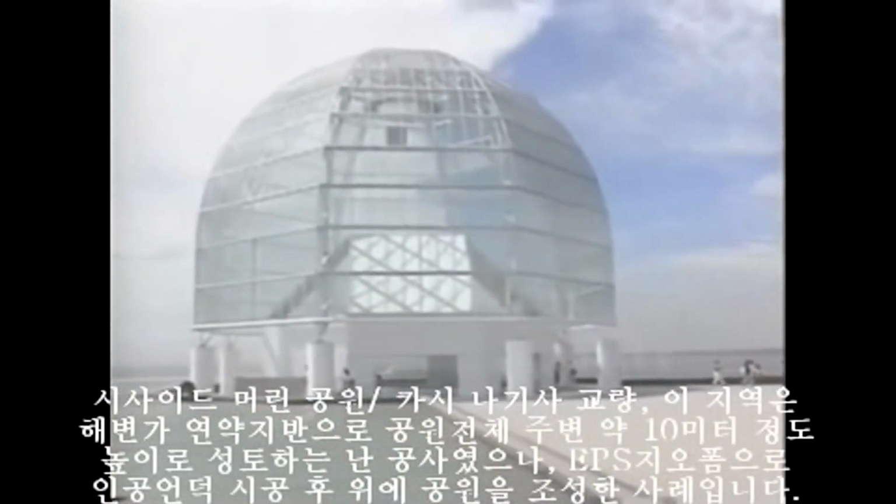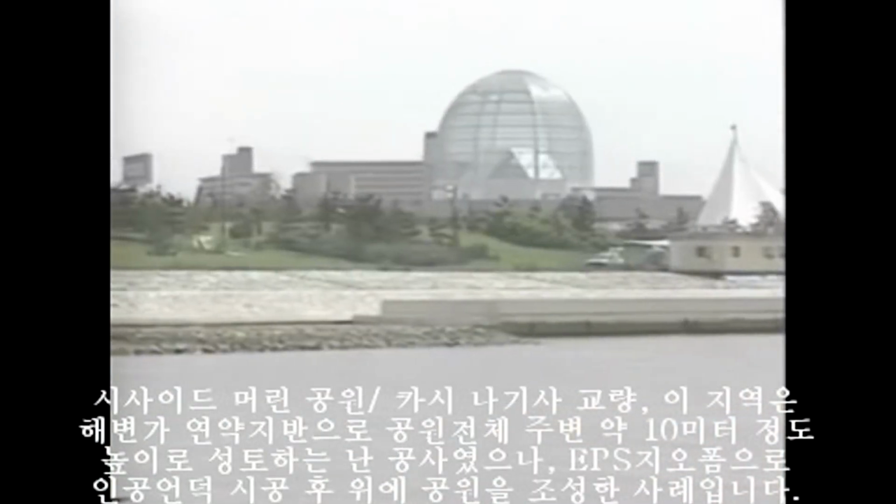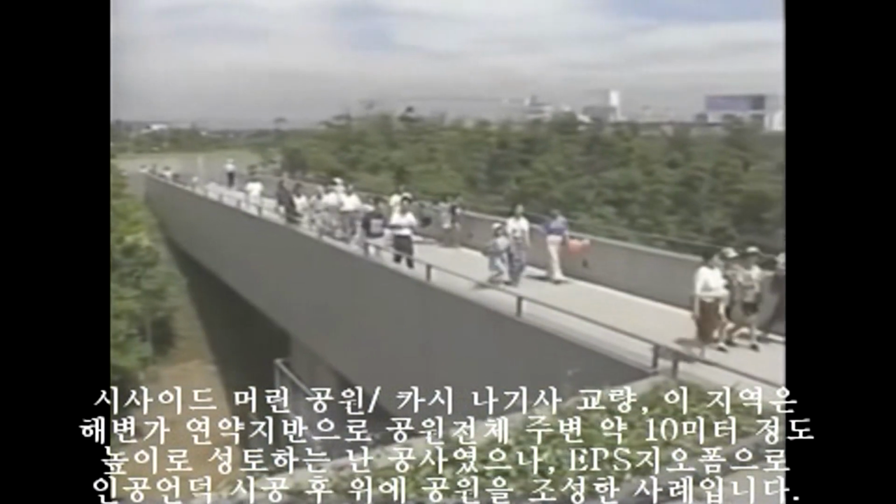The Kasi-Nagisa Bridge and the adjacent seaside marine park are constructed almost entirely on weak ground, about 30 feet thick. Here, the EPS construction method was employed to create hills within the marine park, and there has been no effect of lateral flow on the base pilings of adjacent large buildings.